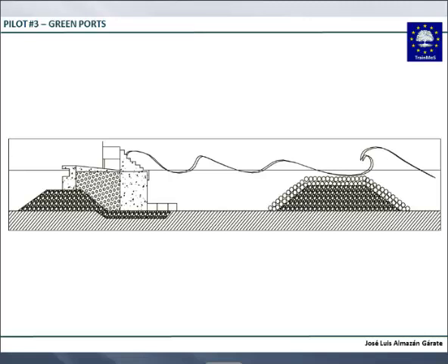And most main ports are within the city areas. So it's quite important not to protect the water with high breakwater structures, but with wide structures. You don't need material here, so it's much cheaper just to leave water within the space between the dikes. This is a new concept in which we have been working a lot and in which we really believe.